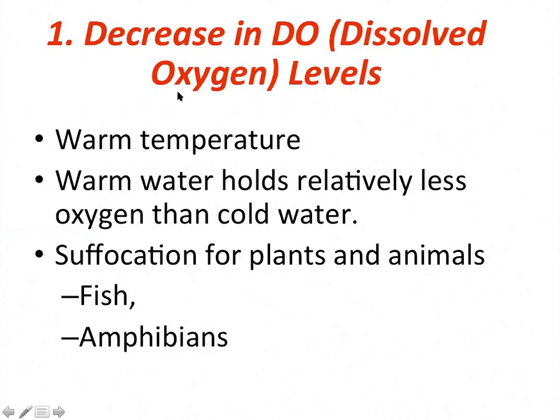This low DO primarily results from excessive algae growth, which is caused by phosphorus in any water body, and this can result in an insufficient amount of dissolved oxygen required for most aquatic life, as a result of which die-off and decomposition of submerged plants also contribute to the low dissolved oxygen.